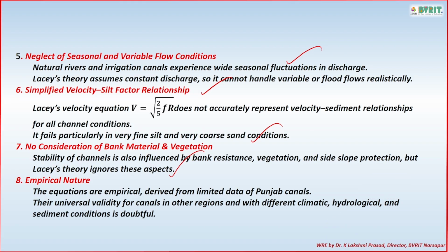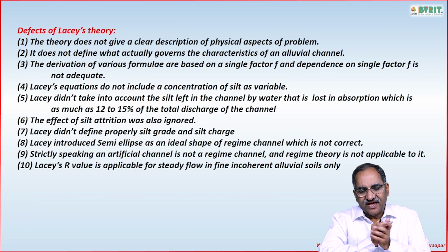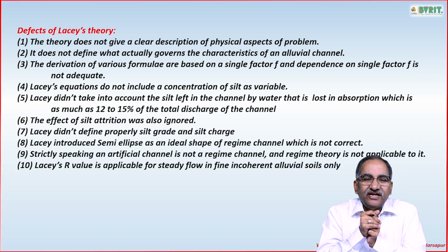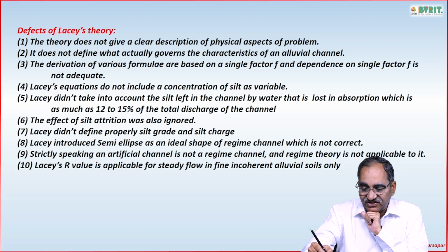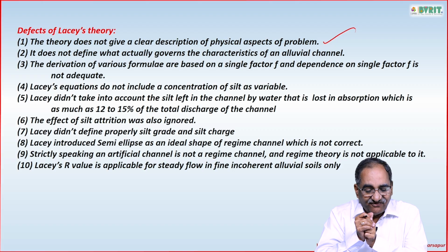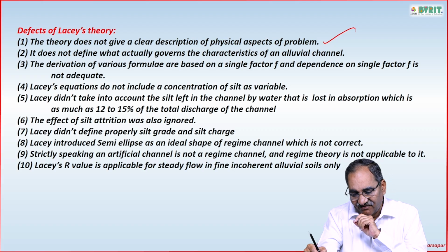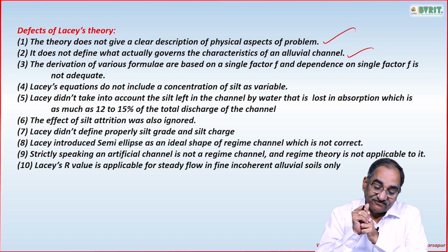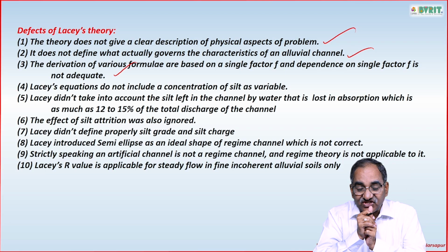Most of the equations of Lacey's theory are empirical in nature and derived based on very limited data available for the canals in Punjab, but their universal validity for canals in other regions with different climatic, hydrological and sediment conditions is doubtful. The same thing I can repeat in simple sentences. The theory does not give a clear description of physical aspects of the problem. It does not define what actually governs the characteristics of an alluvial soil. The derivation of various formulae is based on a single factor, which is not adequate.